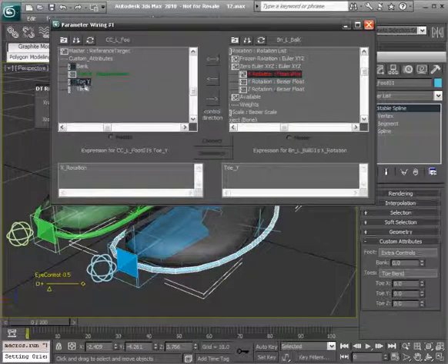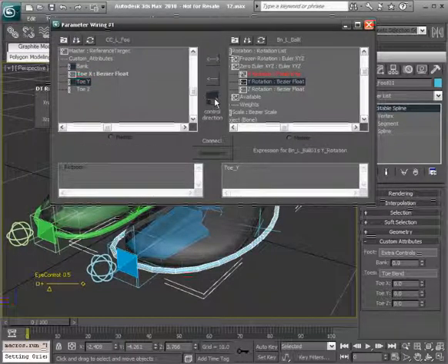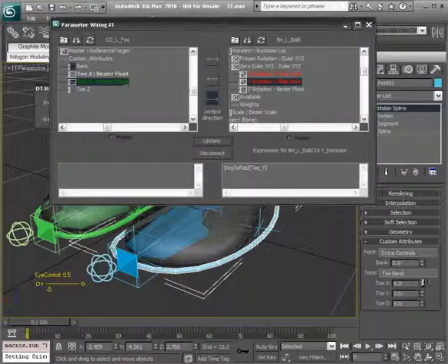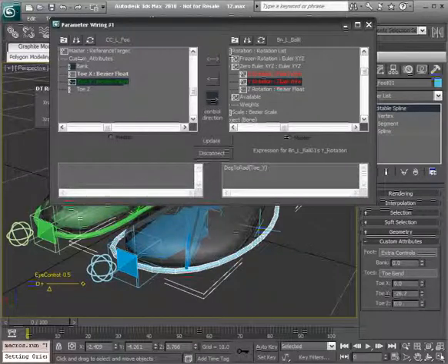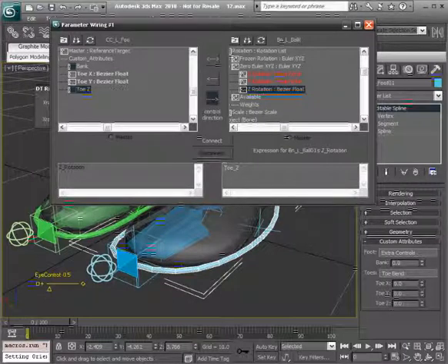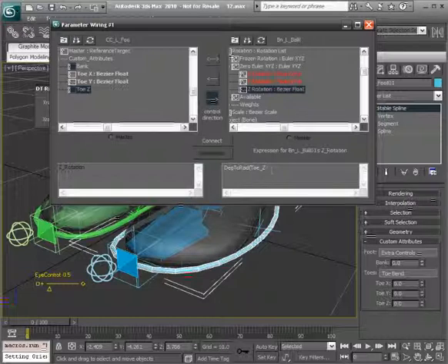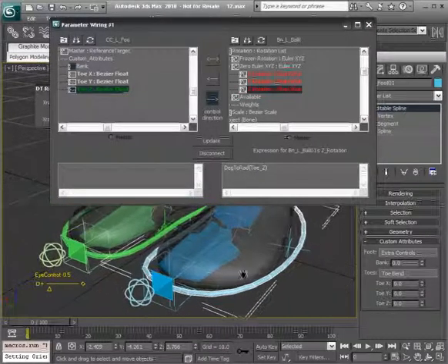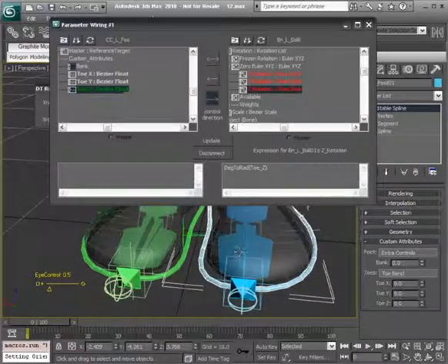Okay, so we're already here. We just need to tie in Y to Y. Choose that bottom arrow, connect, deg to rad, put toe Y in parentheses, and choose update, and then test. Great. All right, so that leaves us with one more here. So again, degree to radian, put toe Z in parentheses, and choose connect. And there we have it. There's our up and down. All right, so that finishes up our toe, and that's it for our left foot control.